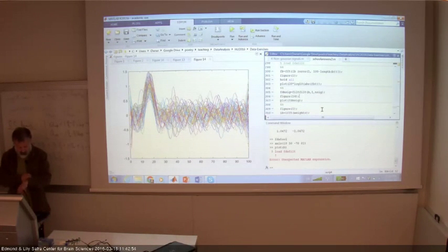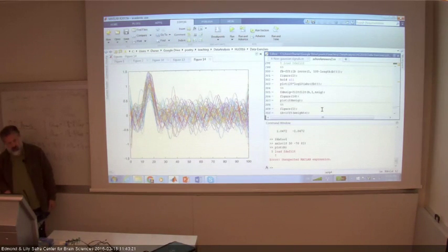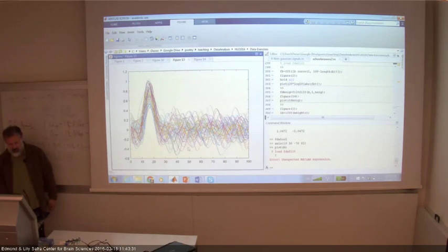Yes. Yeah, because sometimes, in this case, the trials are short. But you may have, again, a situation in which you want to filter millions of samples, and then you don't want to do the FFT on millions of numbers and calculate the windows. You want to have a filter. Also, I shouldn't take the weights too seriously. It worked better in this case. I know that this is the best signal-to-noise ratio I can get because that's the theory. But this is incidental. It's because I used the best filter for the specific signal that I put into the data.